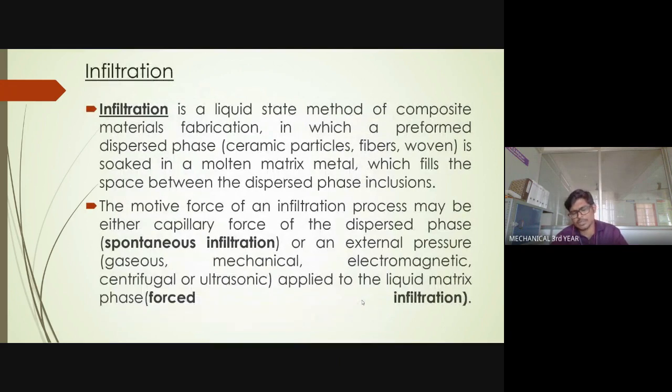The first method is stir casting method. The next method is infiltration method. Infiltration is a liquid state method of composite material fabrication, in which a preferred dispersed phase is soaked in a molten matrix metal. Okay, so you can see over here, it is soaked.